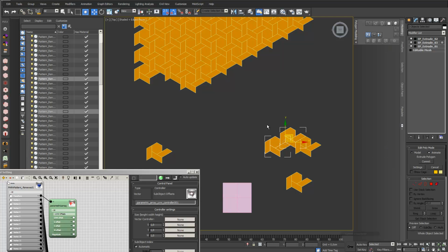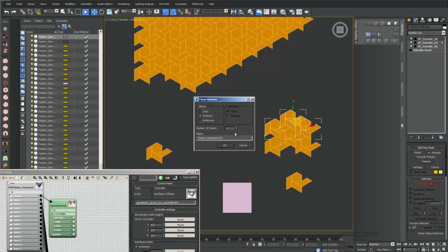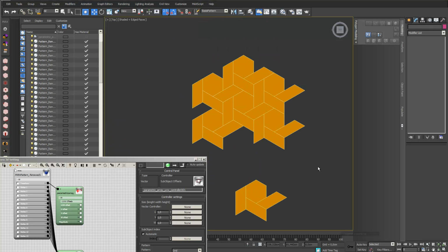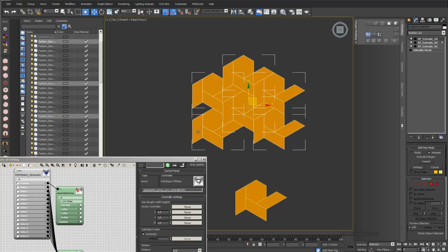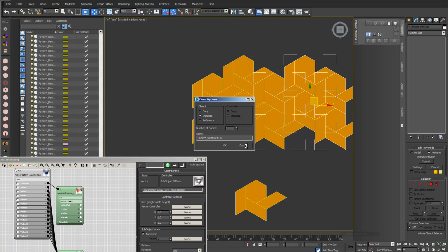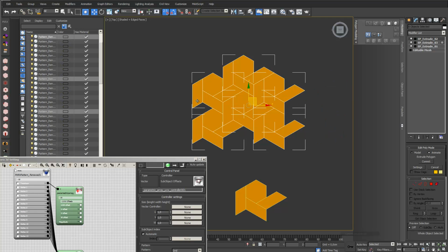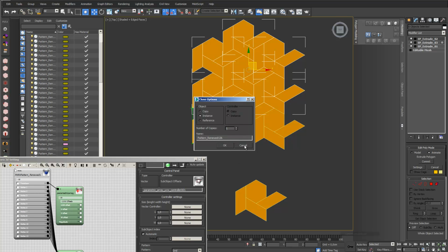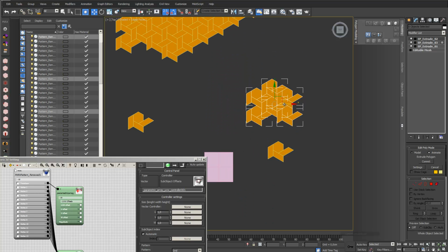So if I copy all 3 of them, then you have a pattern with 3 by 2, and if I select this, you can see that with element number 3 it's repeating. If I take element number 1, I can move it on top of element number 3, and it's repeating. I can do the same thing in the vertical direction. I just take my first one and copy it to this position, and this means that the whole thing is working as a pattern.